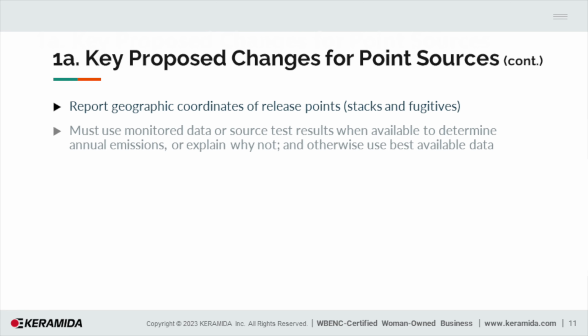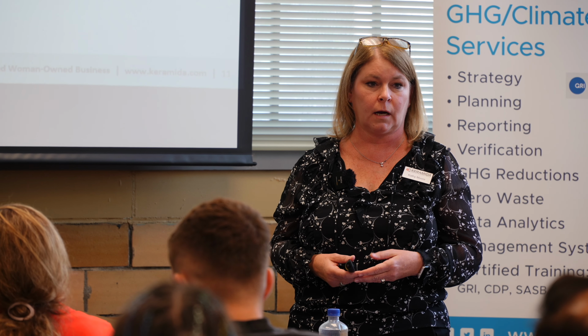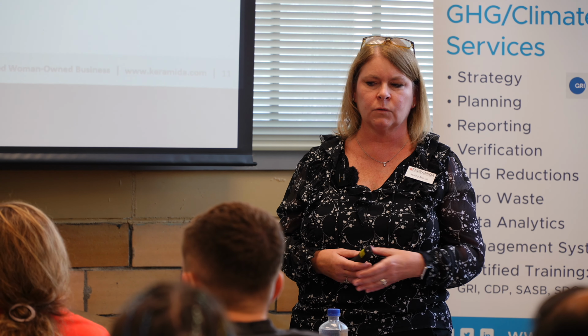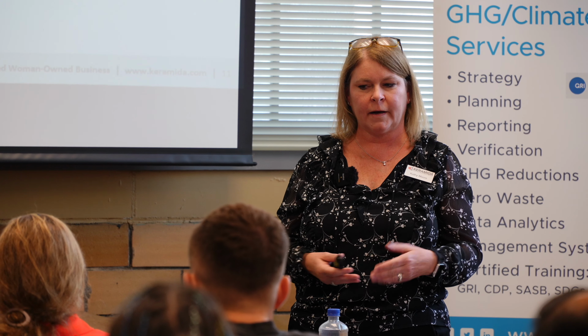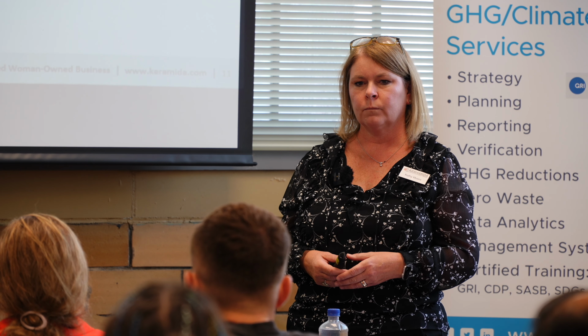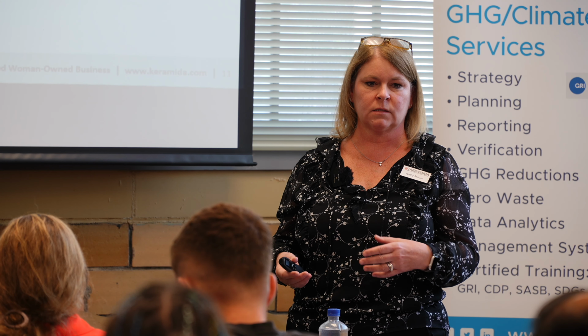When you're reporting your data, EPA wants you to use your actual stack test data if you have it, which is always typically the best information you're going to have because it's going to be accurate to your facility. If you're not going to use your stack testing data, then you need to tell the state and tell EPA why you're not going to use that. Other data sources that can be used for calculating your emissions are EPA tools such as AP42, WebFire, and other resources. You can also use site-specific data where you test specifically just to get an emission factor for a process.